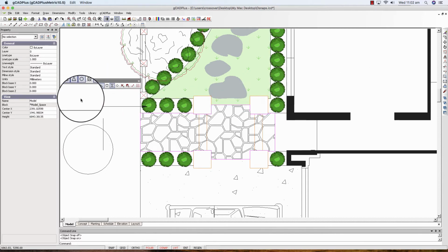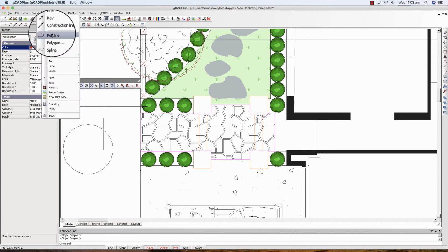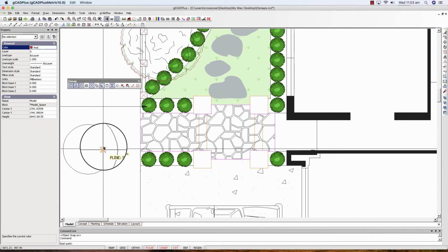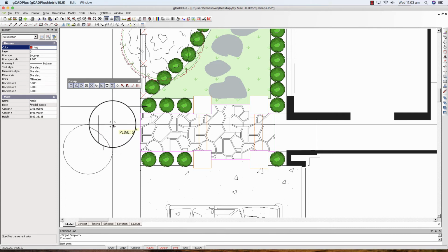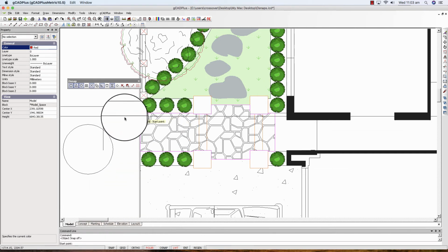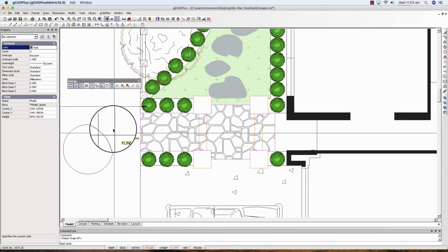So now let's go again to draw a polyline. Again, I'll change my colour to red, so draw a polyline. Now I want to find the end of that line. It finds it very, very easily, and I can go nearest, and that all works just nicely. But if I now hit the F3 key, the object snap is off. If you come down here, object snap is off, and we want an endpoint. See how we cannot find it.